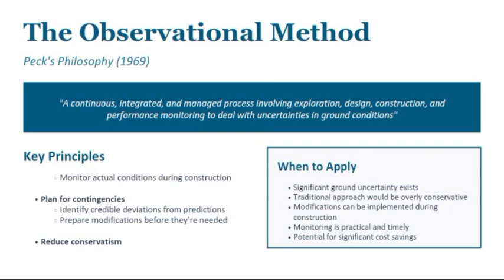Now, this philosophy has three main principles. One, you predict likely behavior before construction. That's why doing observation doesn't mean that we are cancelling prediction. So predict before construction, still observe actual behavior during construction, and then there's an adjustment of design or construction methods when the conditions differ.